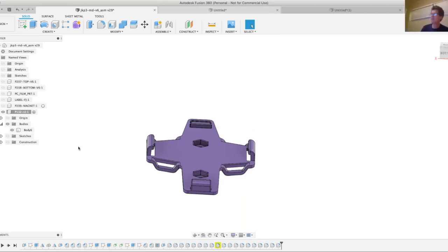Generally, you would use components to see interference, because when you create multiple bodies inside the same component, if you join them, it will join any areas of overlap. You can do the intersect to do an intersection of the two, and that's something that's not done that often.